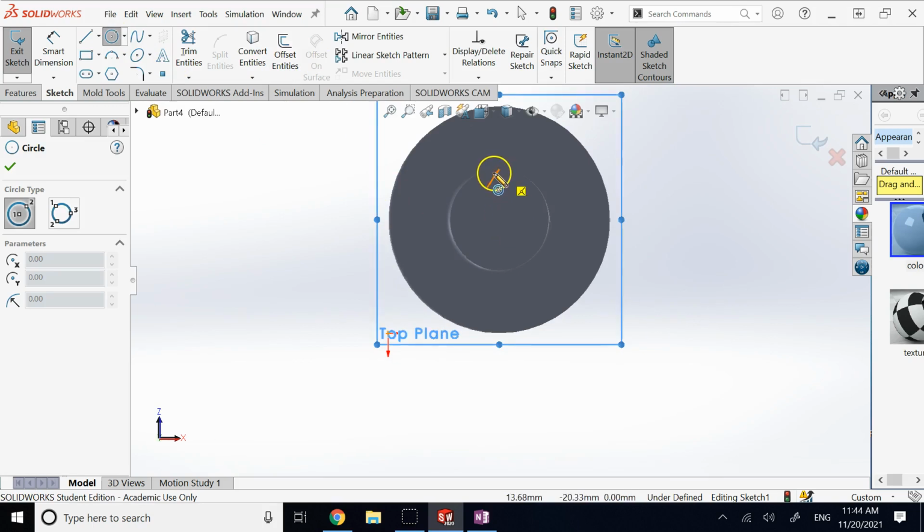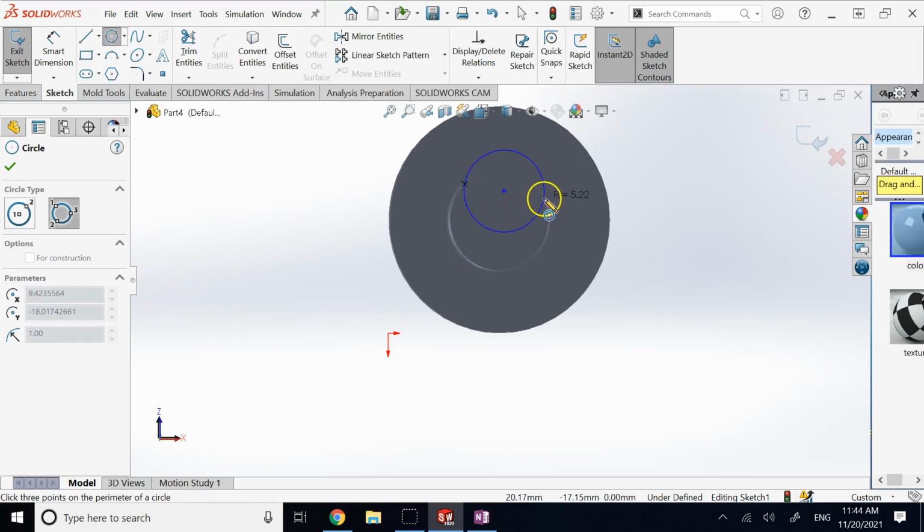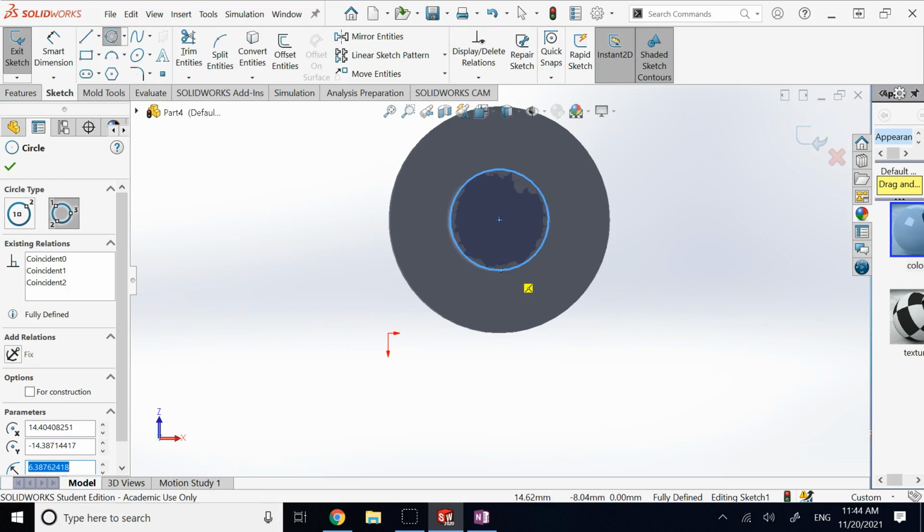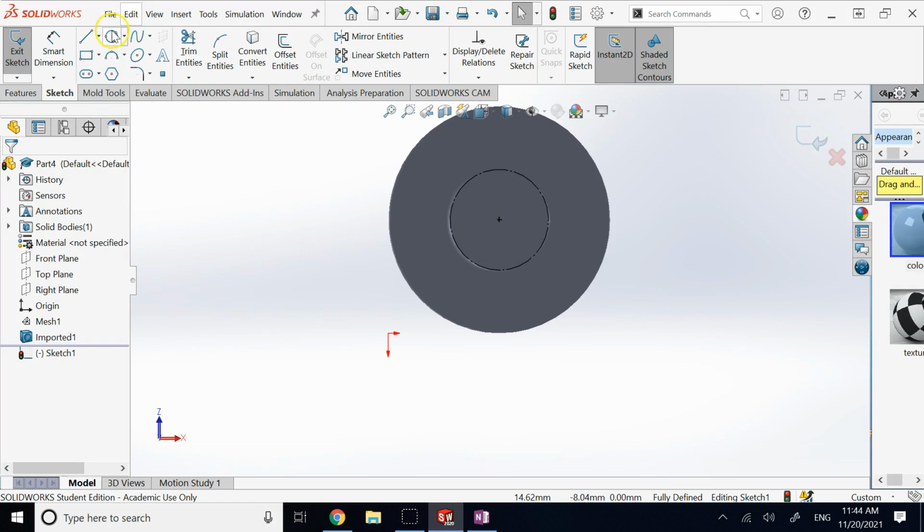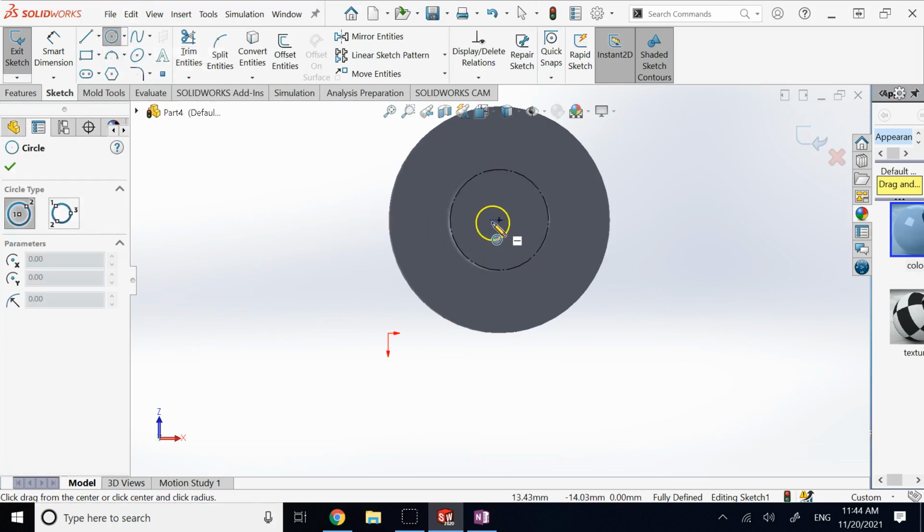And if I want, I can get that circle to match the original circle of the shaft here. I can use the perimeter circle and click on three points on the mesh surface points. So this is that original circle, and I can use it for construction.